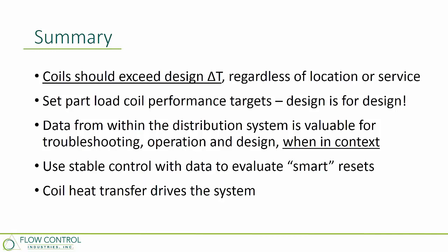So if that chilled water coil, we put that at the top of the pyramid, and that's what's going to drive the rest of our system design and operation, we need to start setting different expectations for performance. We can't pick that one metric and say that that's good enough. We need to start looking at it in terms of what should it be and how do I get that operation out of the system, because that is going to dictate the rest of my system.